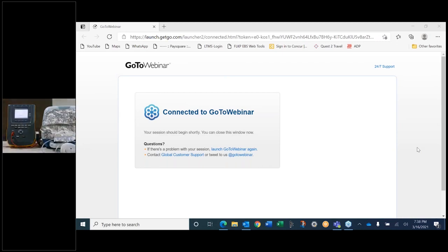Make sure it is touching that medical device completely. Yes, it is touching the medical device completely. You may need more tape in order to make sure it stays where it needs to be. Yes, we are going to put the tape so that it will be better. We have wrapped it and then we are going to test the touch current now.